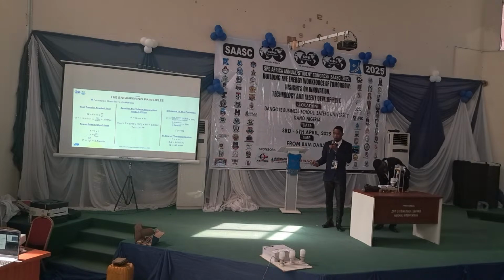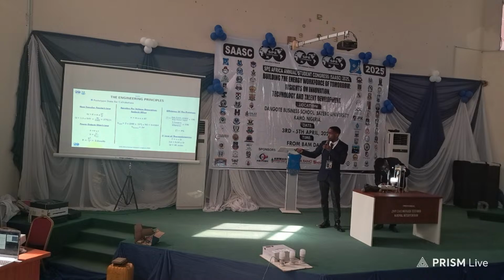Now, speaking of the Seebeck effect, we used 2 thermoelectric generators, and from the specifications, we had a Seebeck coefficient of 200 times 10 to the power minus 6 volts per Kelvin, multiplied by the temperature gradient, as I explained here. We have 0.036 volts, which is being picked up.